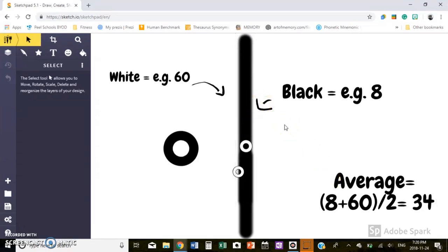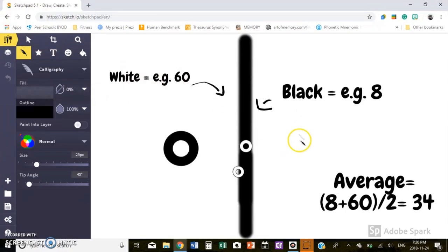So let's say we have the speed at 50%, exactly along the target. It should be going at 50 power. Well, all we're doing is getting an error value. So whatever the robot is sensing at the moment, let's say it's sensing 60 at the white, minus its target. So let's say this is 34, the average, and that's just 26.